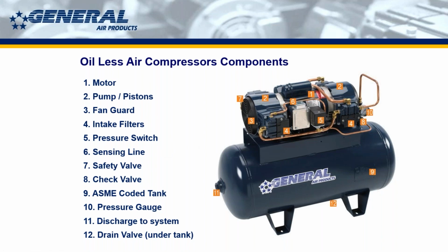So that's really important to know and to be looking at those on occasion. That's the biggest thing as far as maintenance goes on these. So if it's in a more dirty environment, you want to look at that on a regular basis. If it's in a pretty clean environment, then it probably isn't going to get dirty very often. But certainly in a warehouse environment, there's going to be a lot of dust. You get into a sawmill or a concrete plant, chemicals, all of those things can beat up the inside of a compressor starting at the intake filter. Something to always keep an eye on.